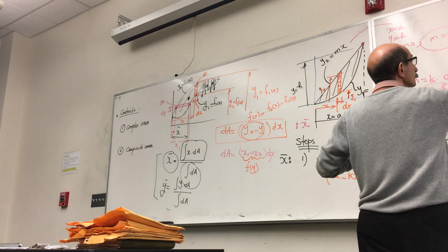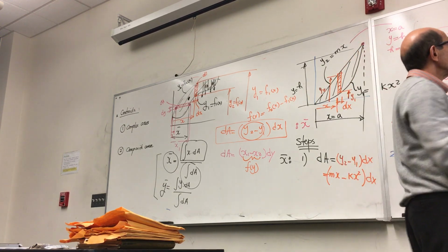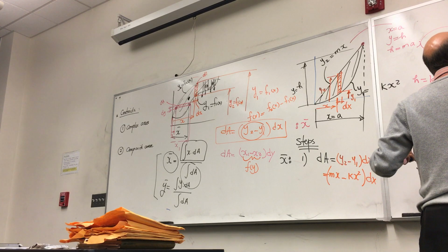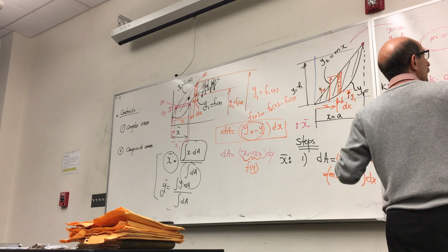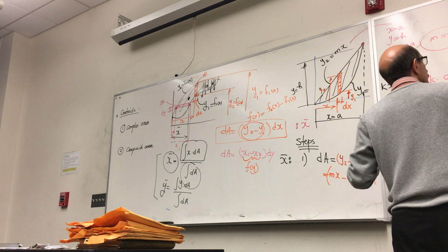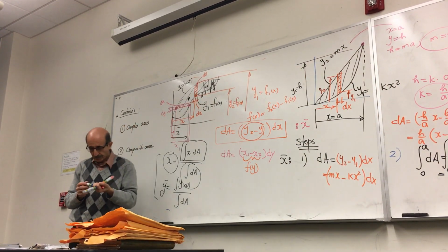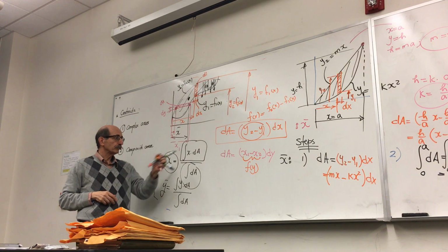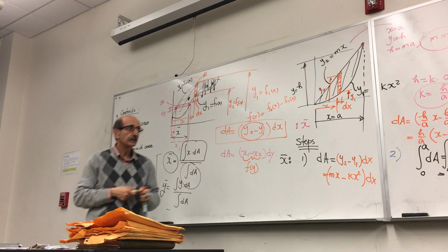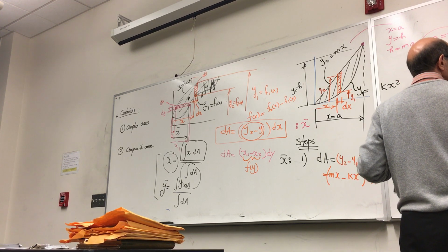So if you substitute that, you have h over a times a squared over 2 minus a squared over 3. This cancels out with that. You have h a over 6. So that's the integral of dA. So that's the second step. The third step, now you just perform finding the numerator. You already have the denominator, you find the numerator. Numerator is easy, right? So step number 3, find x times dA.